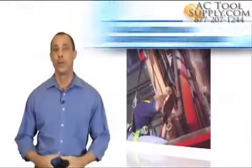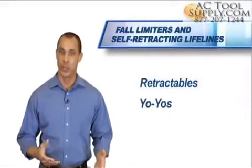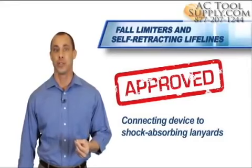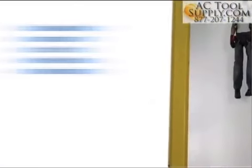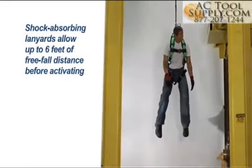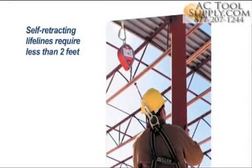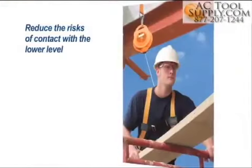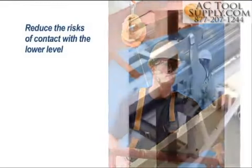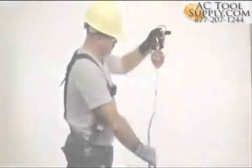Fall limiters and self-retracting lifelines, sometimes referred to as retractables, yo-yos, and seat belts, are approved alternative connecting devices to shock-absorbing lanyards. While traditional shock-absorbing lanyards allow up to 6 feet of free fall distance before activating, self-retracting lifelines require less than 2 feet. Shorter activation and arrest distances reduce the risks of contact with the ground or lower level obstructions and allow for easier rescue in the event of a fall.